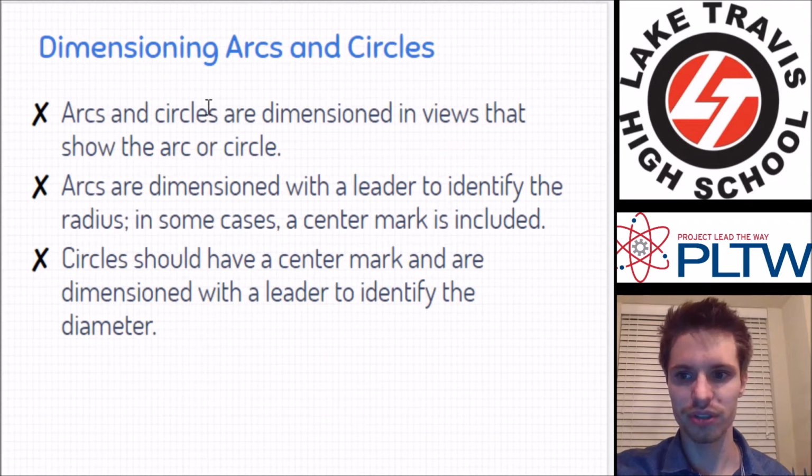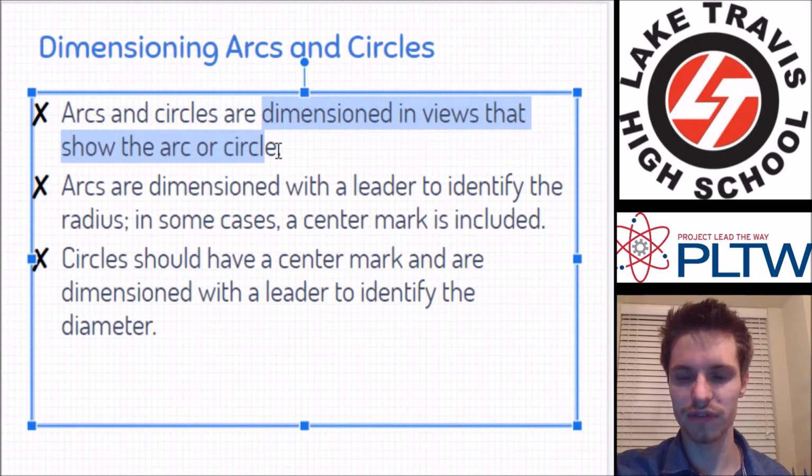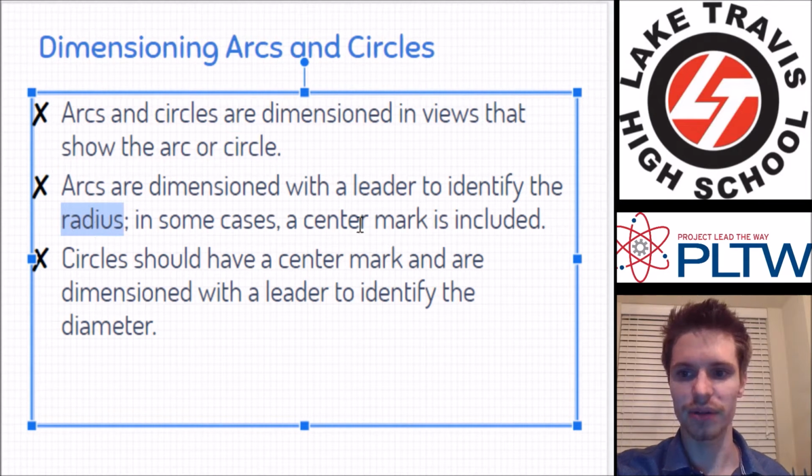Okay, so when you dimension circles and arcs, remember that you want to dimension it in the view that shows the circle and arc. That's from the dimension guidelines from before. Arcs are dimensioned by radiuses, and sometimes you want that center mark. We'll talk about that in a second. Circles are dimensioned by a diameter.